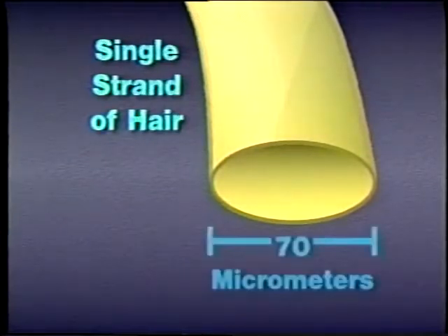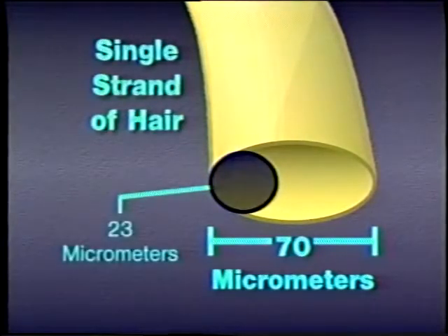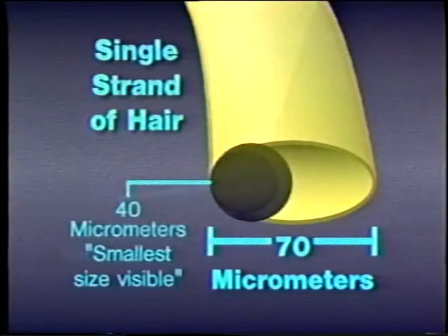The end of this shaft of hair, which is about 70 microns or 70 millionths of a meter across, is 3 times as large as the acceptable size for particles in hydraulic fluid. In some systems, even that would be too big. That's pretty small. In fact, it's less than the smallest thing most people are able to see. That means you can't tell by looking whether hydraulic fluid is as clean as it should be.